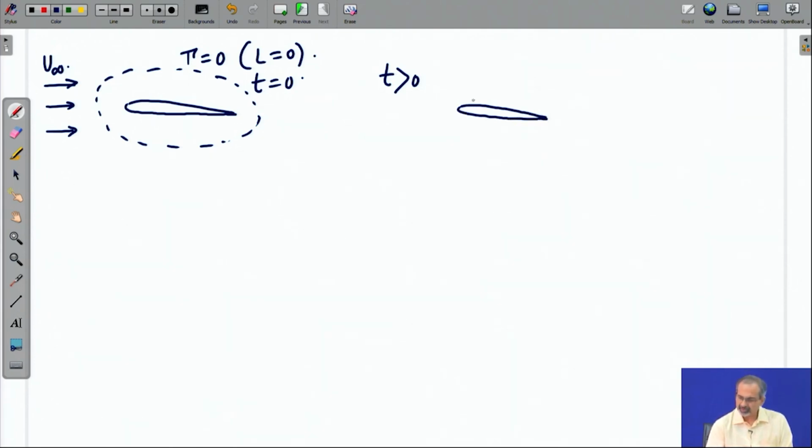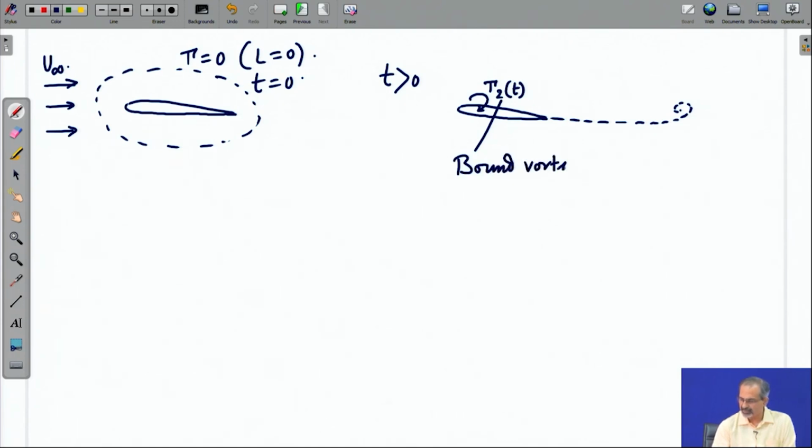the pressure distribution came up on the airfoil, and instead of distributing the vorticity all over, let us say that we mark a single vortex associated with a circulation gamma 2, which we will see very soon, because we want to mark gamma 1 elsewhere, which we call the bound vortex. So, instead of a distributed system of vortices along a vortex sheet, for example, we have it lumped at one point, which we call the bound vortex.